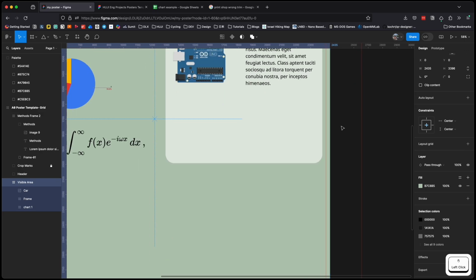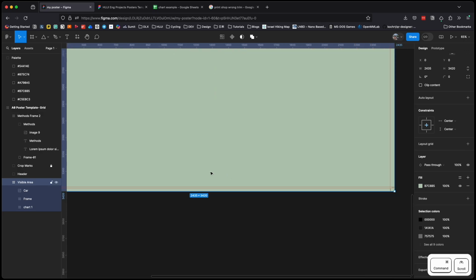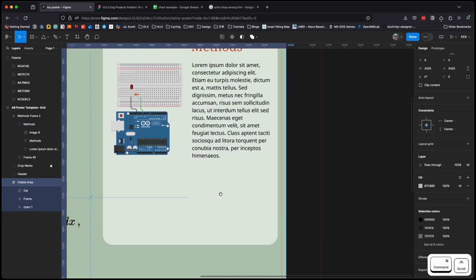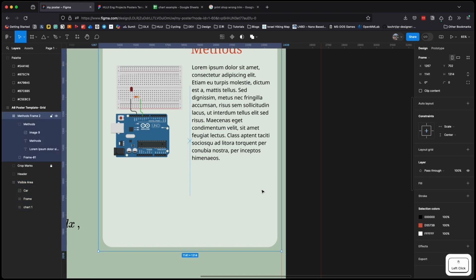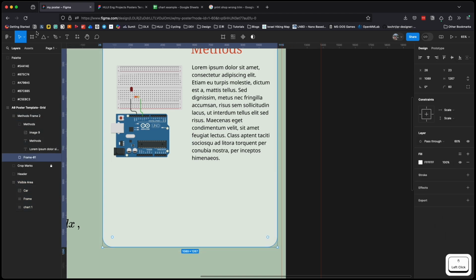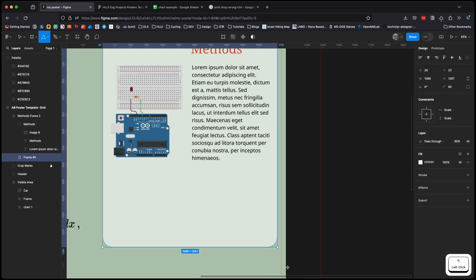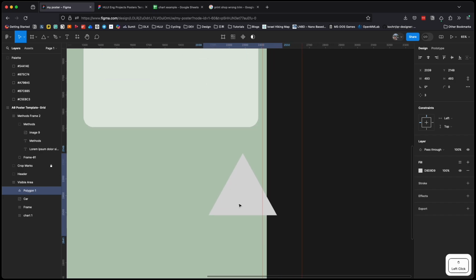Okay, both sides. So pay attention that any element that needs to be sitting close to the background and trimmed should be bleeding outside, should have this bleed. This goes also for boxes, so if you want the box to touch the side of your poster, it should be bleeding slightly outside. Okay, it should have a bleed. So let's say I want this polygon, for example, to reach all the way to the edge, so I make sure it bleeds a little bit.